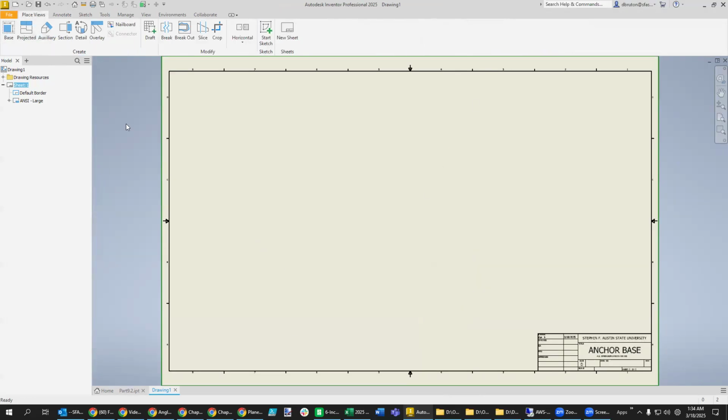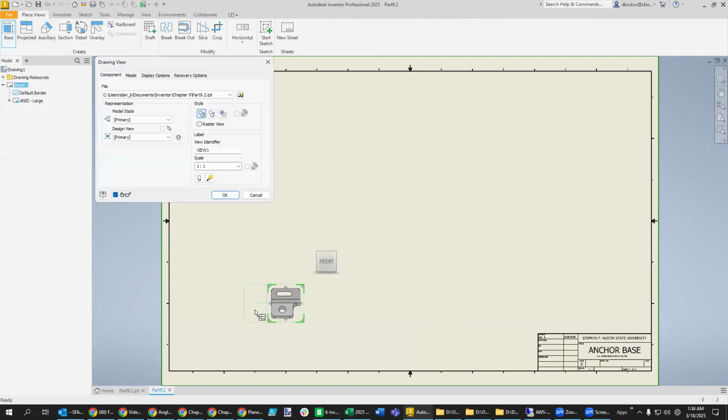You know what to do. When we have a drawing, we go over here to place views. We always have one base, and it needs to be the front view. That looks really good. But you can see this is not taking up much space. So let's go to like 3:1. That looks good. We can move it up a little bit, anticipating the lineup over here horizontally.